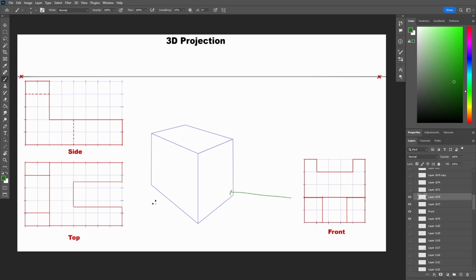So I'm going to start with the side view since it's the easiest part to start with and the most representative of the object. Now the side projection is 8 units long, so we have to divide the left side of the box into 8 equal parts. We can do that by drawing the horizontal line, connecting it to the horizon line at a random point, and divide that area into 8 equal parts and project it back into the horizontal line.